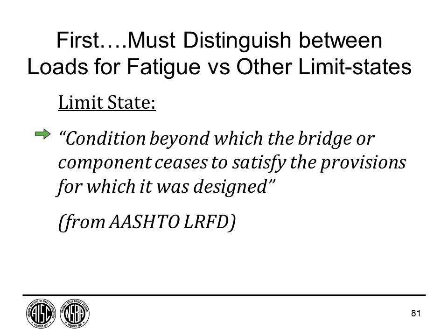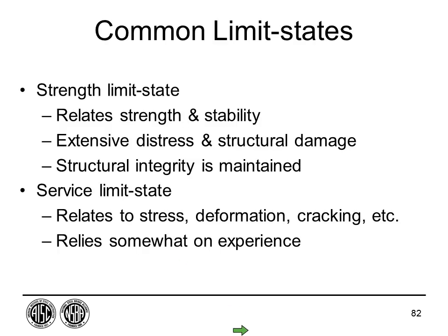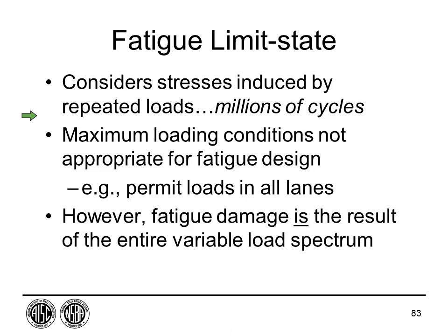It couldn't carry the load. But realistically, we also have to think about other limit states: deflection, serviceability, of course, and fatigue. So the common ones, like we said, are strength and stability. We're more worried about the other one, fatigue, and that's what we're focused on today. But fatigue is a little different. It isn't a single event. It's repeated events. So the fatigue limit state has to include a time factor, if you will.